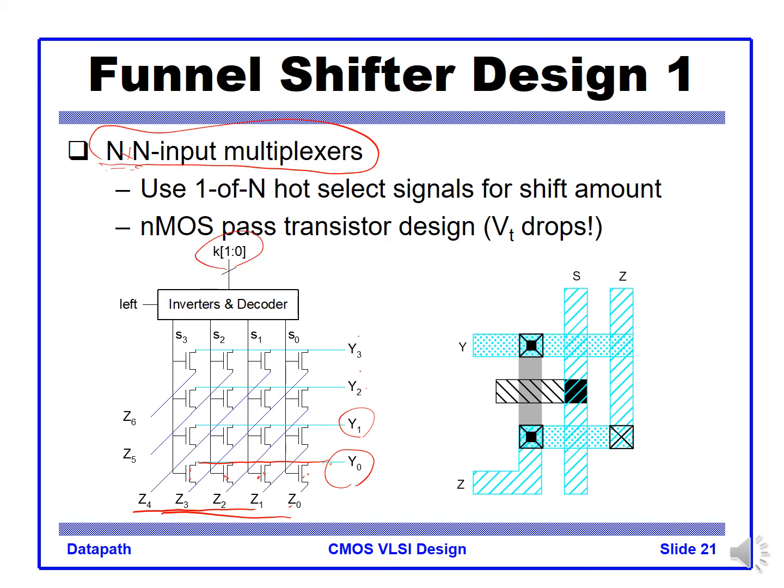The control offset bit determines the amount of shift operation. We need to have the capability of inversion, right? If the left shift is selected, then we have to invert the k, right? Otherwise we just pass k. Then we decode it, and select only one of the selection signals, that gives us the shift operation.